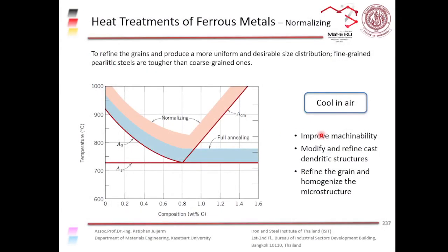So that's why we have to do a different heat treatment process, like normalizing. When we do the normalizing process, we get rid of all the dendrites. So we sort of break off the different branches and make them into different grains. Okay, so we have a more normalized, more equal grain size instead of one long grain with different branches.